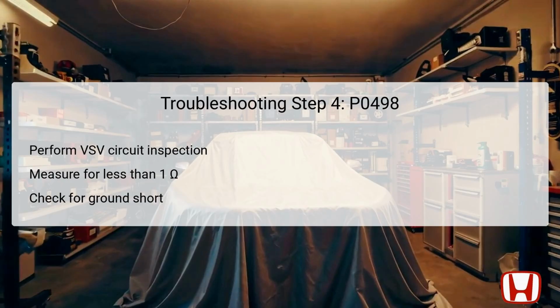Additionally, perform checks for a short to ground. If any of these conditions are found to be abnormal, it confirms the existence of a fault within the circuit that needs addressing, either by repairing or replacing faulty wiring or connectors.